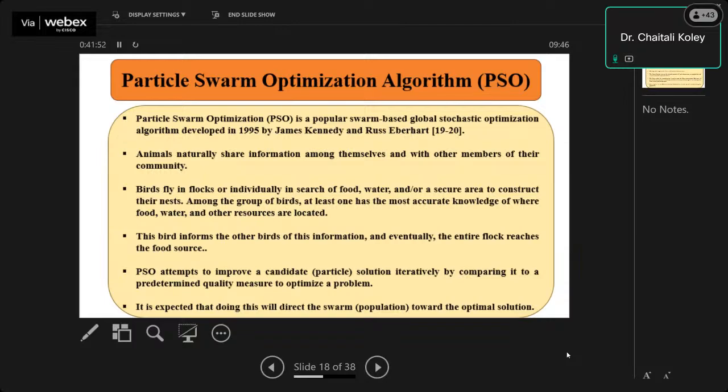And for any antenna, not necessarily the FSS, first of all, whatever the antenna parameters are, length, width, height, substrate width, you have to do a lot of parametric analysis. Based on that parametric analysis, the resonating frequency may change, the bandwidth may change, and all those things you can consider as a data set. So you have to create your data set depending upon which type of design you are going to implement. Okay.